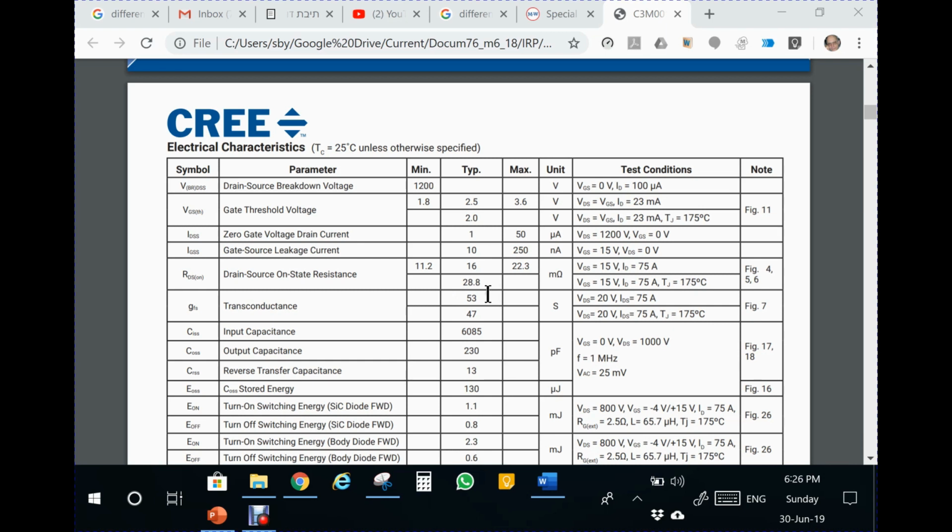So obviously the resistance is going up, RDS on is going up, and this is, of course, on the one hand, not very nice because the dissipation will go up, but on the other hand, it helps if you use a number of units like this in parallel.